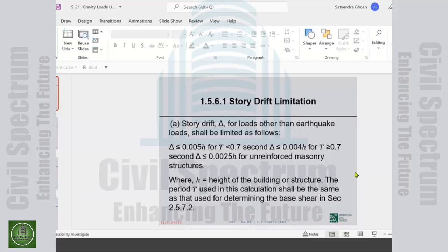Is it permitted to assign partition wall loads as uniform pressure loads instead of line loads? That's what I was trying to point out; I apparently wasn't very successful. For movable partition loads, I have never seen anybody doing line loads with them.